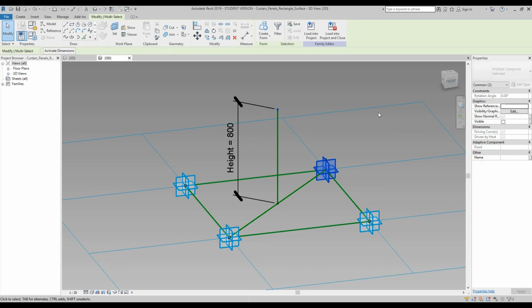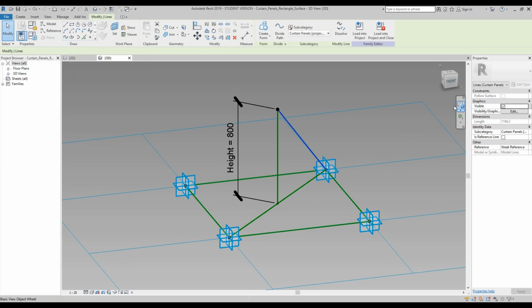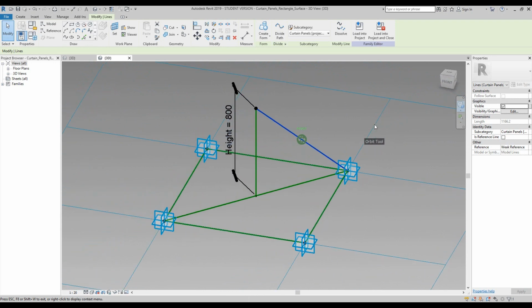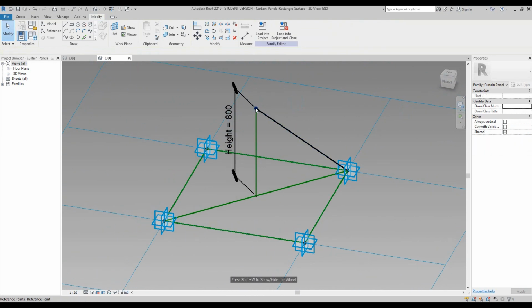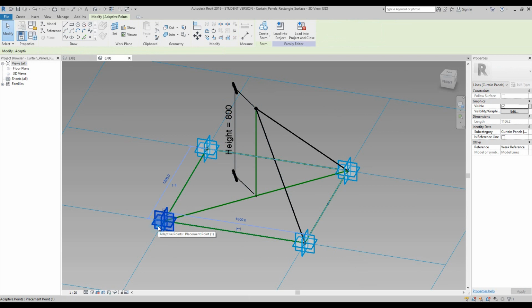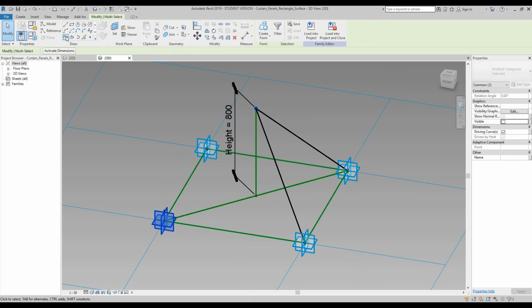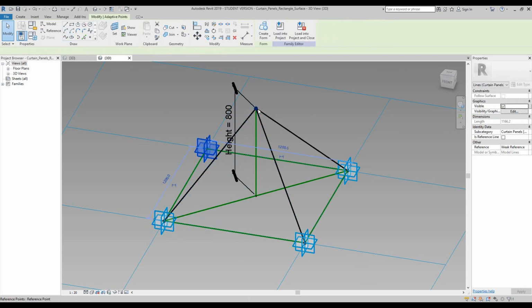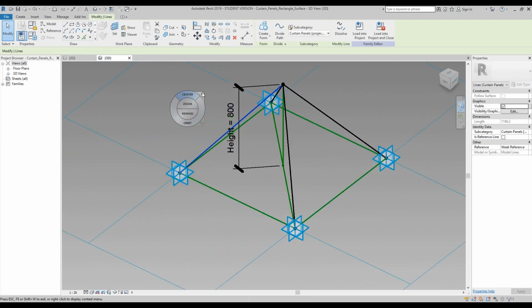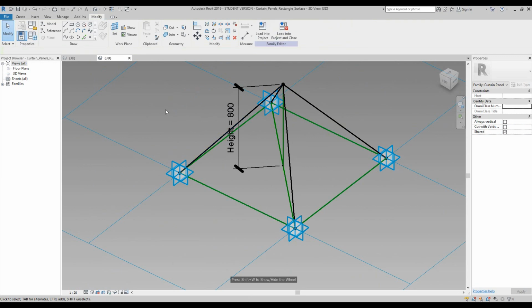And with those two selected, if we go over to our draw section and choose spline through points and click, you will notice that it automatically adds a line. So we're going to do that to the other 3 points. We select our middle point, then our other placement point, and then go up to spline through points, and again. We'll continue to do that on all of them. Now once you've done all of them, I'd like you to press in negative space so nothing is selected.